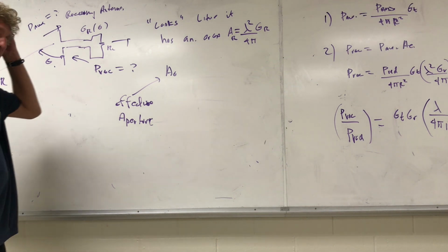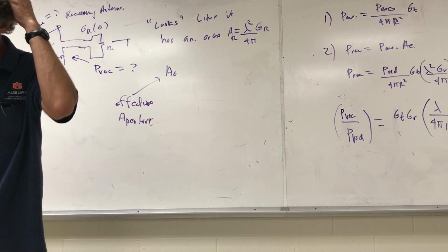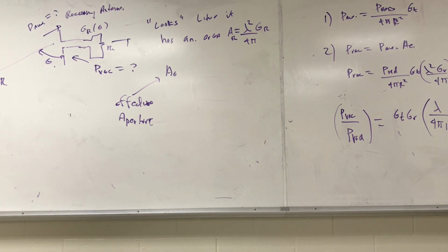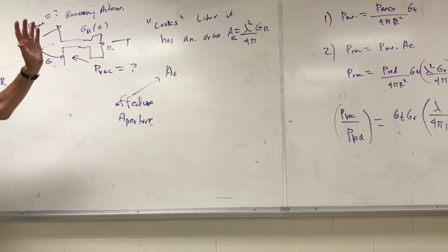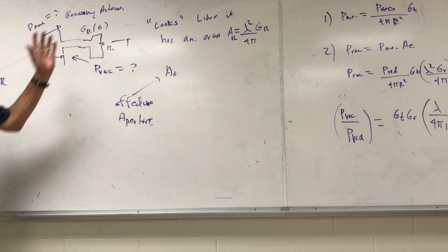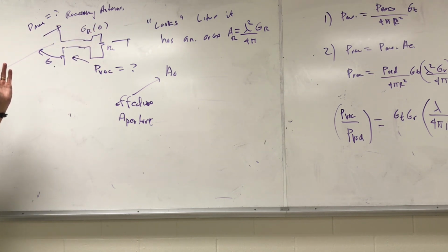That's something that doesn't come out in Dr. Wentworth's discussions, but is so critical. Even though the antenna receives, say, 30 watts, the best we can ever extract from that 30 watts would be 15. And that's if everything is matched perfectly. Are you with me, class? It's a very important concept.